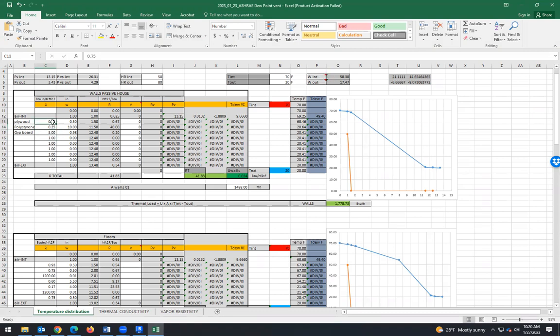Okay, but what we have to understand is that thermal insulating materials are materials in which the thermal conductivity is around 0.2, 0.3, 0.1. And for other non-insulating materials, the thermal conductivity is much higher. Then we have to go to the manufacturer to see what is the actual thermal conductivity that we're going to use. Anyway, that would be the first option. I recommend you do this a few times.